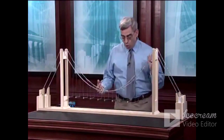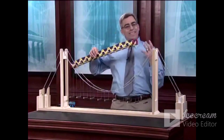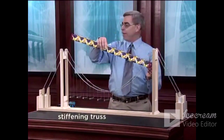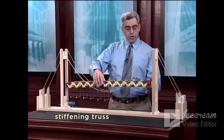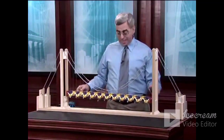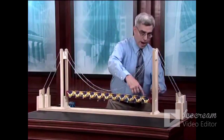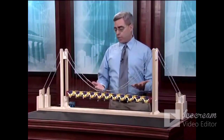And that's why most suspension bridges, to include the Brooklyn Bridge, use a secondary structure called a stiffening truss, which is supported directly from the cable. And I do want to emphasize that the stiffening truss is not resting on the towers. Note that there's a space between the ends of the truss and the towers. It's entirely hanging from the cable.